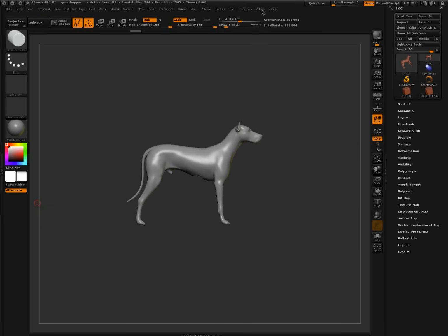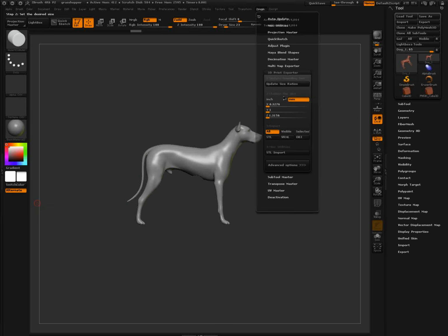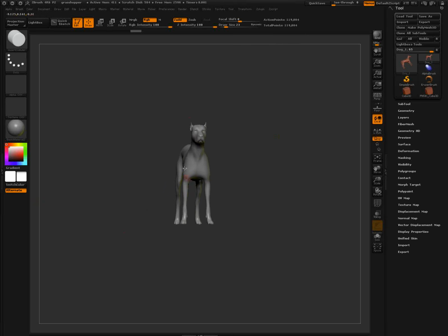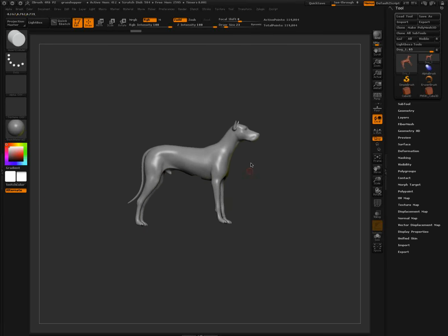When you hit update size ratio, if you have inches on or millimeters on, it's literally, in essence, creating a bounding box like it does in any other application, looking at it and seeing what that actual mesh is in millimeters or in inches. So you want to click that update size ratio before you even export.